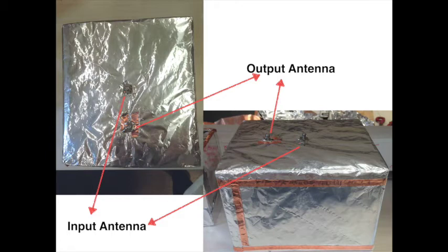And I put the two antennas on the locations I described on the previous slide. Basically, I had a 6 centimeter long copper wire for each antenna, and I soldered it to the middle part of the port, as shown, the square metal piece. And I soldered the ground plate of the port, which is the square part, to the cavity resonator using the copper tape, because you can't solder on aluminum, and it actually just burns. So I had to use copper tape for that, and it makes it more firm, because we don't want it to be moving and changing direction inside the box.